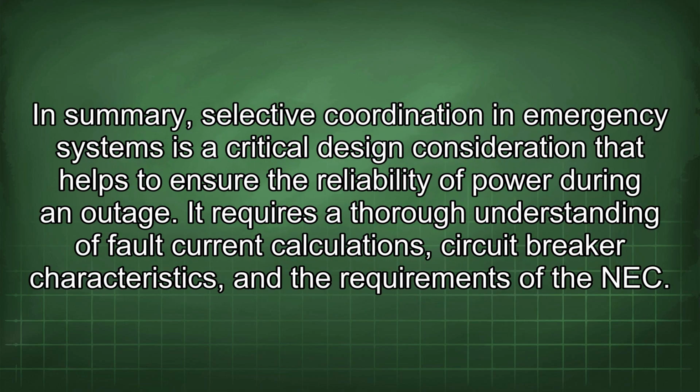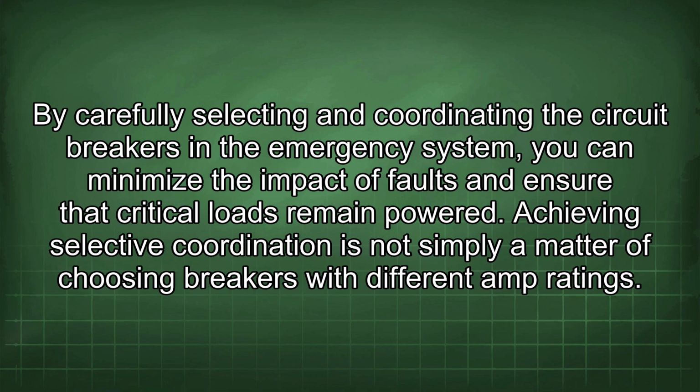In summary, selective coordination in emergency systems is a critical design consideration that helps to ensure the reliability of power during an outage. It requires a thorough understanding of fault current calculations, circuit breaker characteristics, and the requirements of the NEC. By carefully selecting and coordinating the circuit breakers in the emergency system, you can minimize the impact of faults and ensure that critical loads remain powered.